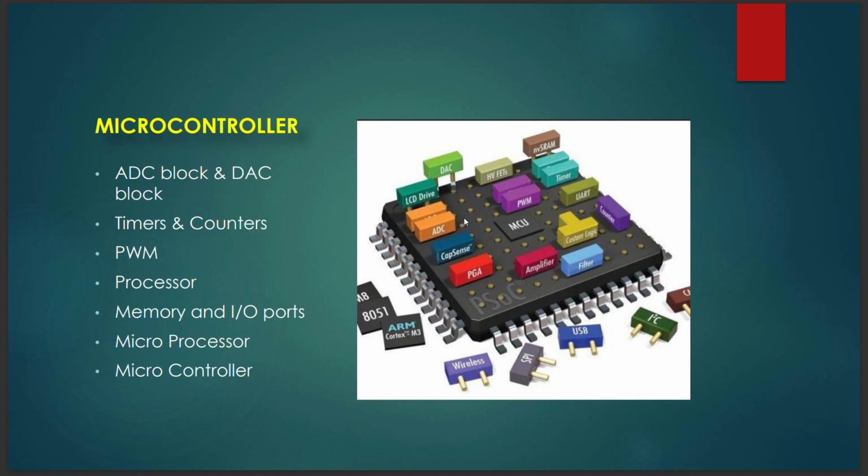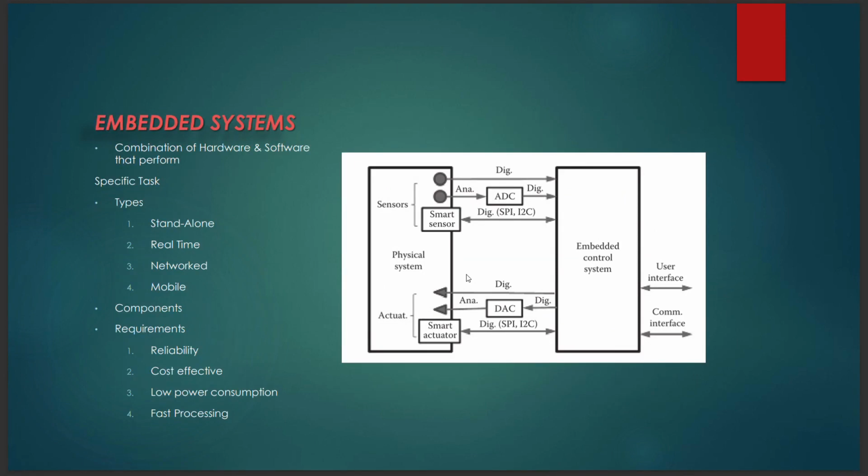A microcontroller is embedded inside a system to control a singular function in a device. It does this by interpreting data it receives from its input-output peripherals using its central processor. The temporary information that the microcontroller receives is stored in its data memory, where the processor accesses it and uses instructions stored in its program memory to decipher and apply the incoming data. It then uses its input-output peripherals to communicate and does the appropriate action. Okay, next we will see about embedded systems.